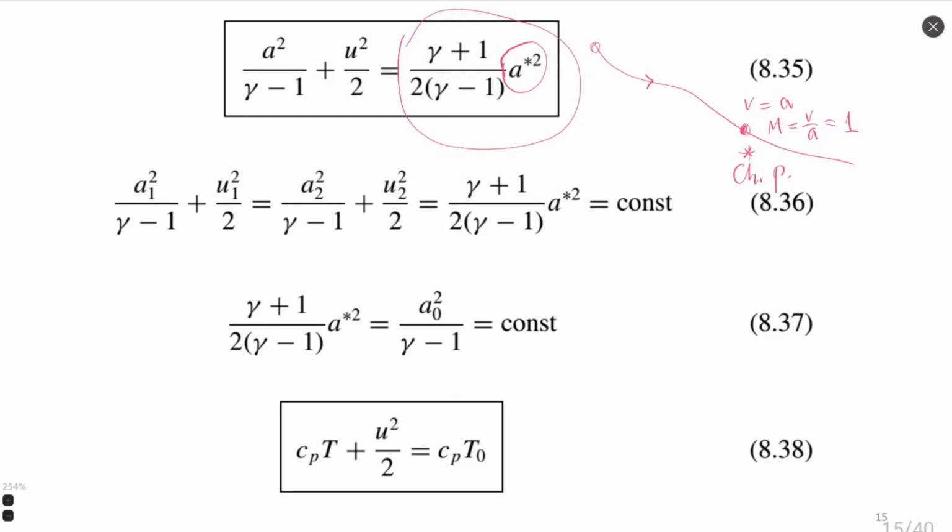Formula 36 proves that when we apply our original energy equation to the concept of characteristic speed of sound, we may see that since characteristic speed of sound is the only parameter we have on the right side of equation 36, this value is constant for our system, same as we had stagnation speed of sound constant for any system. Characteristic speed of sound is also constant for a closed system.